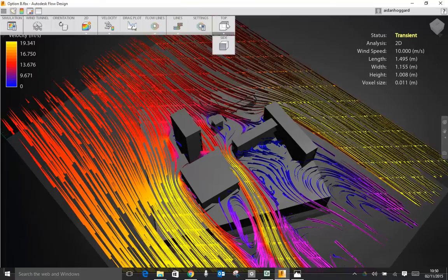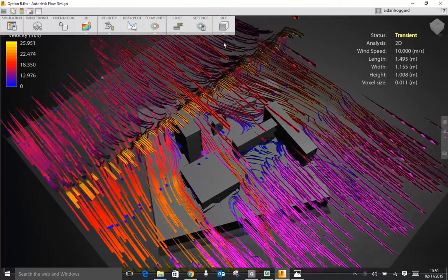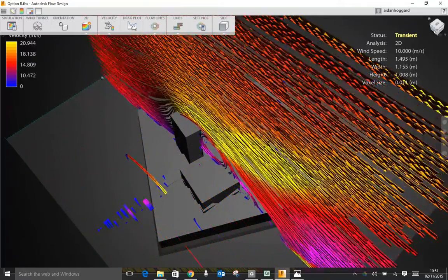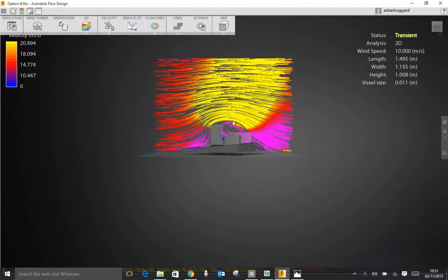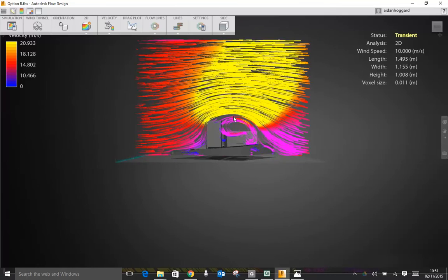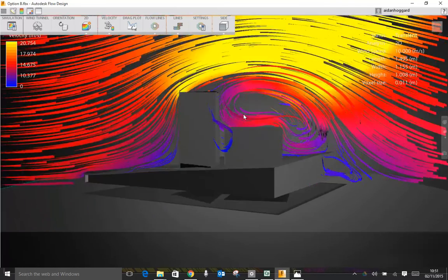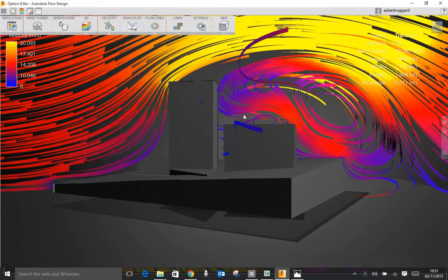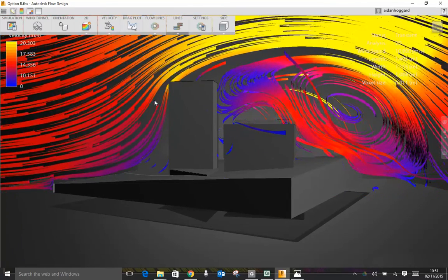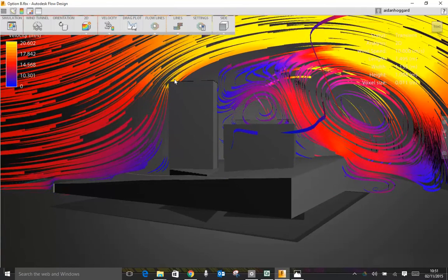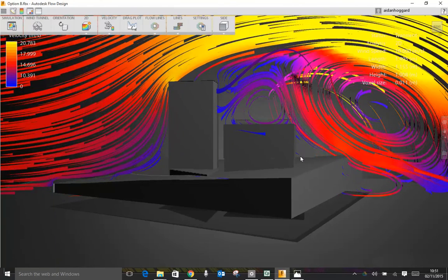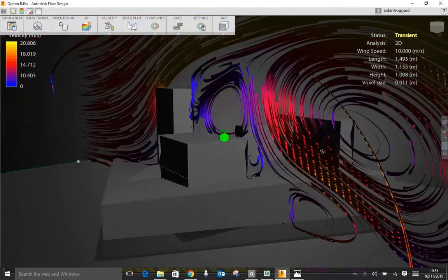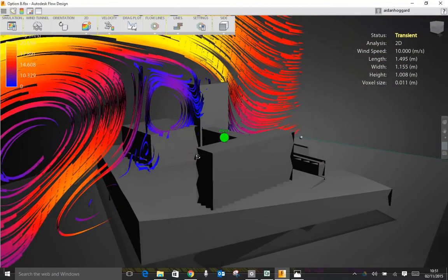Lines, settings. Okay. And again, the top view, side view, you can change. So we're now viewing those flow lines in a side view. Now again, I wouldn't get too concerned about a high level wind flow around your building. I'm not really asking you to consider what's the implication of that wind velocity flowing over the top of your building. That's a little bit high level. But what you might use the side view for is to perhaps look at, are there any concerns on your exterior spaces?